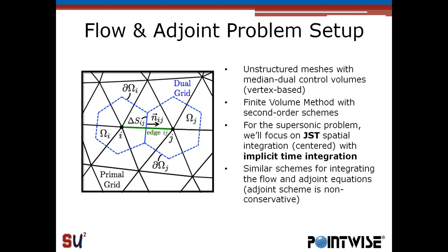One of the nice features of the continuous adjoint that's in SU2 is that it results in a continuous PDE that we can go ahead and solve using a lot of the same, or at least similar, numerical methods to the flow problem. So we can reuse a lot of the machinery inside of SU2, a lot of the object-oriented class structure, to solve both the flow and the adjoint problems. And there are some small modifications that are important, but the idea is that we can reuse a lot of the structure.